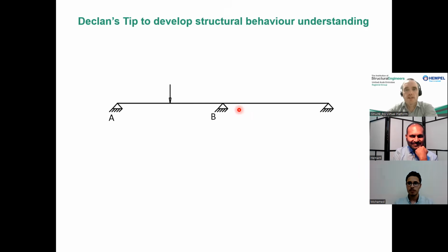In this example, you have a two-span beam with a point load in the middle of the first span. When you're trying to visualize the bending moments and the reactions, you may wonder, for example, reaction C, is it going upwards or downwards? You've got a force on the adjacent span.